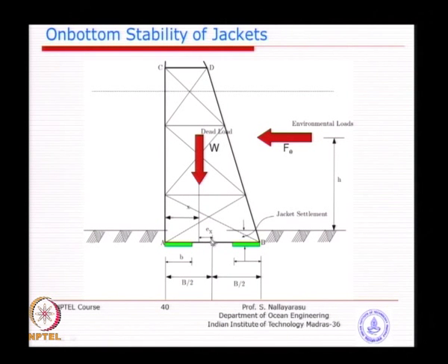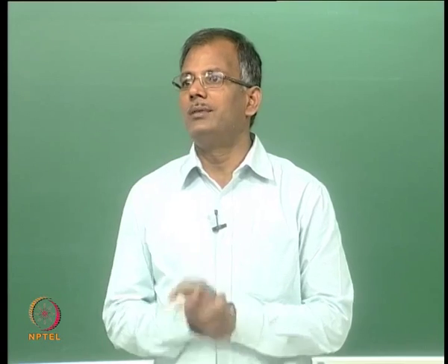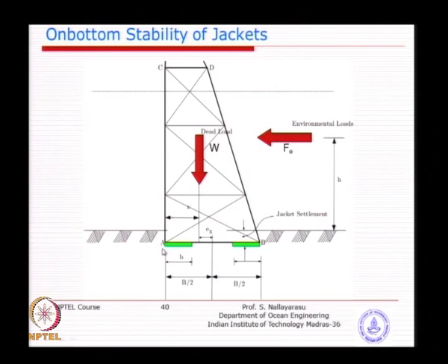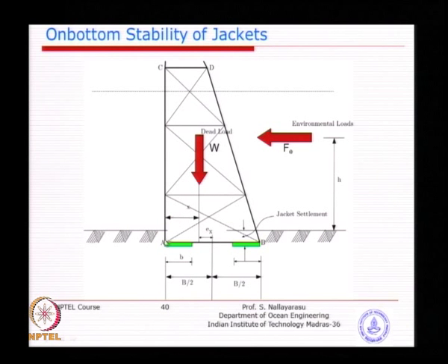Now, if the center of gravity keeps moving towards the vertical face, which is what we are worried about for instability, it will cause a lesser factor of safety. So, the distance x is more important. Every time you evaluate the rotational instability about a particular face, you need to find the CG of the system with respect to that face. As long as you know Ex, you can find x, because the location of the geometric center of the mud mat is already known to us. So, this Ex will be given. Ex is nothing but your x center of gravity or y center of gravity from the geometric center, and the distance x is of more importance.